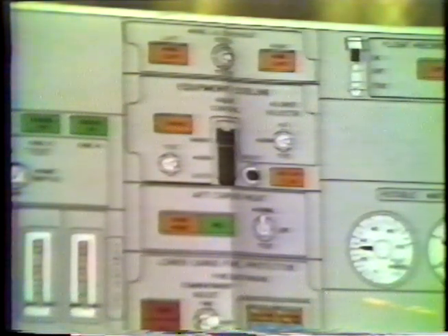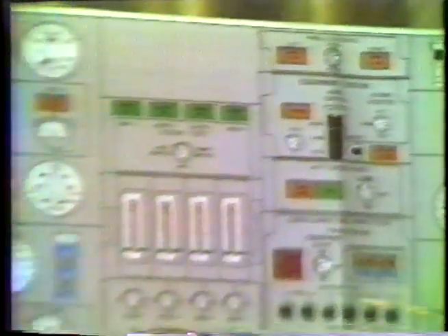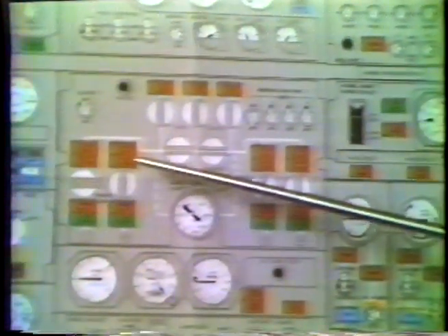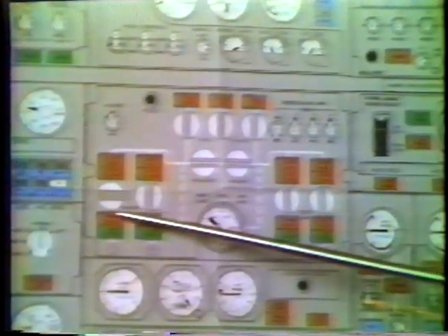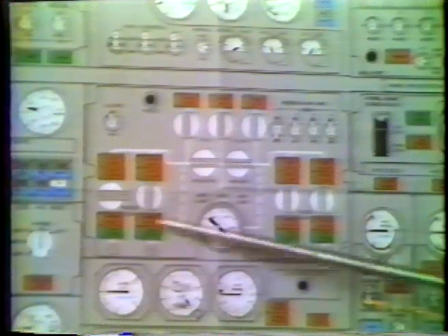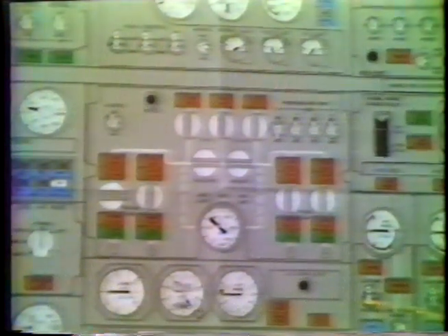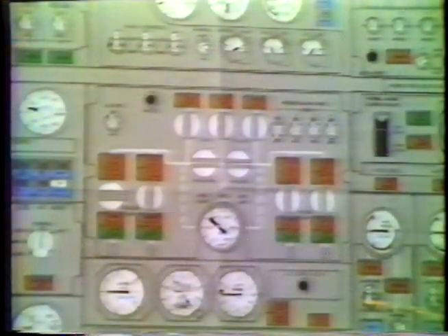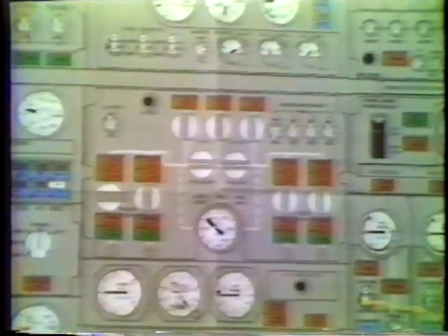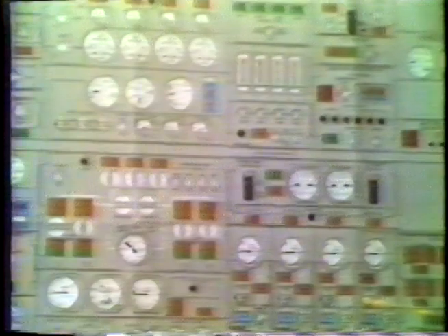However, since it also senses around the bleed valve, it may be upstream of the bleed valve and it may not go out. And then you could reduce the bleed pressure by reducing the engines 1 and 2 one at a time to see if the light goes out. As I mentioned before, sometimes these are faulty and the light comes on when there actually isn't a problem occurring.